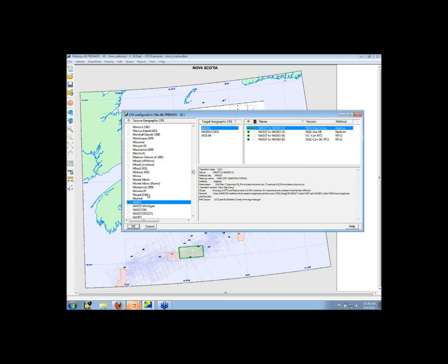So I can go over here and say, when we switch over from NAD27 to NAD83, or do the transformation from NAD27 to NAD83, I can set exactly the transformation that I want people to use right over here. And that gets saved to the site level, and so everybody's using the same transformation. That's really important because different transformations are designed to preserve different properties, like, for instance, length or area. So it's very important that you're using the right one here.